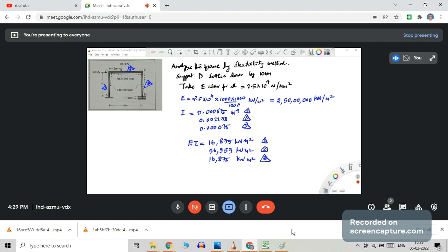That is the way to do it in the stiffness method generally, because our coordinates are generally active degrees of freedom, so they are generally rotational in nature, and at supports generally we don't have those degrees of freedom, so such coordinates we don't select.